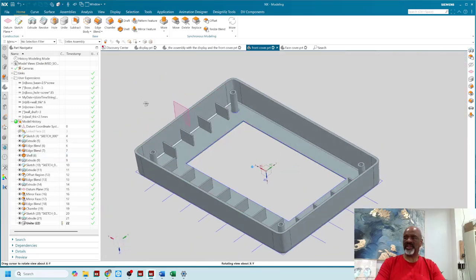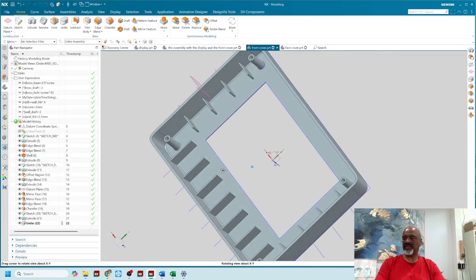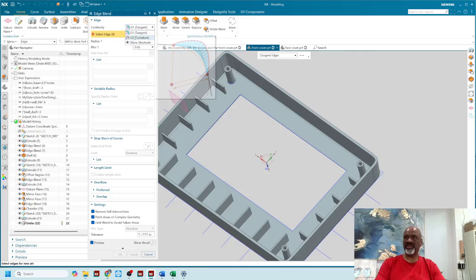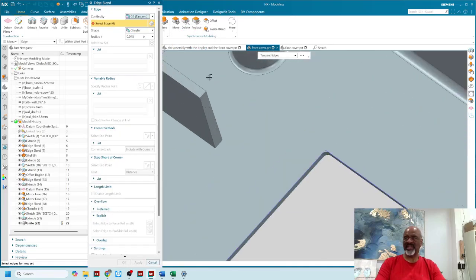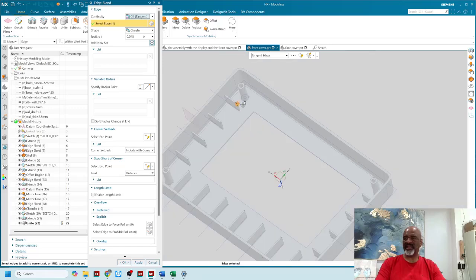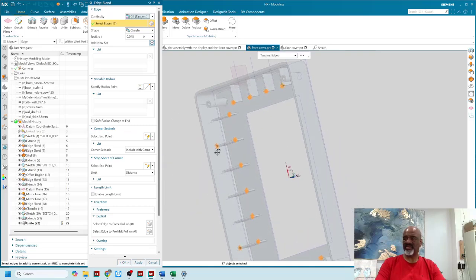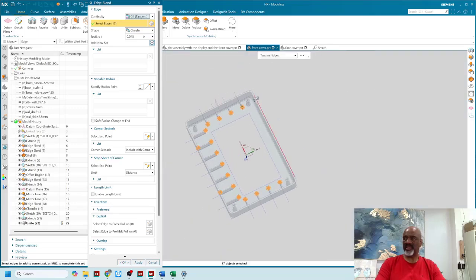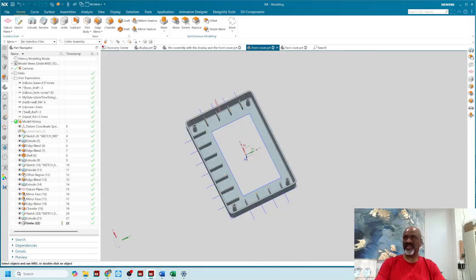And then I also want to give it a little radius so it flows better. But first, I'm going to do a radius here. Now this doesn't have to be G2. This could be a G1. It's not even cosmetic. And I'm going to do that and hope that when I hit the select predicted objects, it does them all, which it does. Thank you, NX. Of course, I didn't want this one. So I'm going to go back. Cancel that. Let's hit that again.